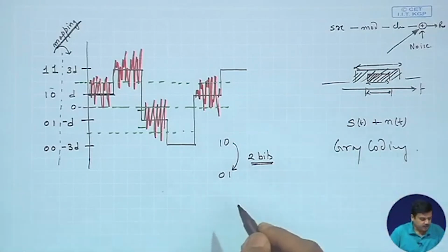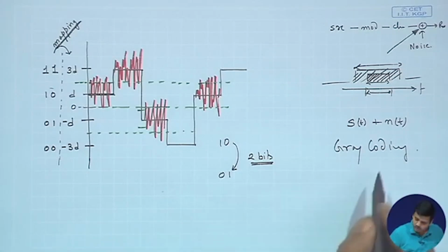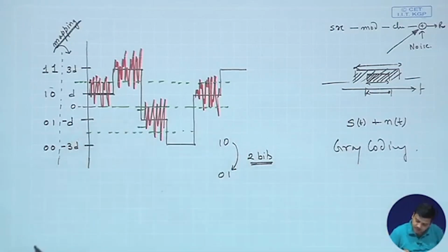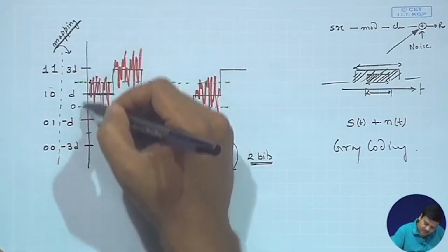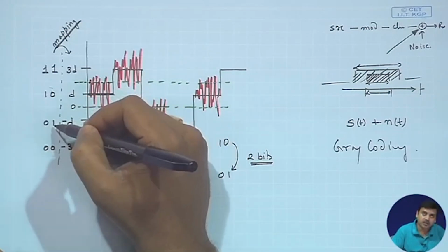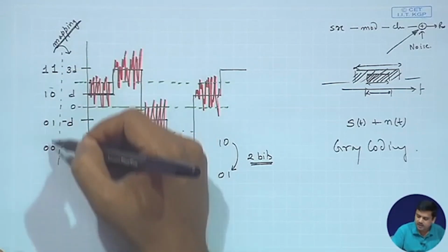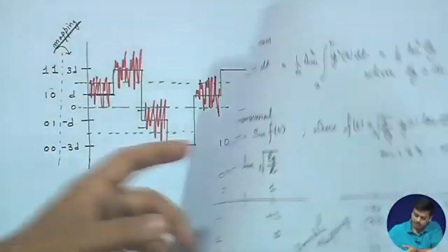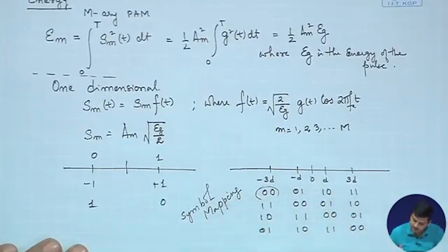The idea behind gray coding is that you would try to map the particular bits to symbols in such a way that when these changes occur, or these neighboring amplitude levels are mapped by bit sequence, the neighboring bit sequences differ by at most 1 bit. So, what I mean is, if we look at these particular possible options.